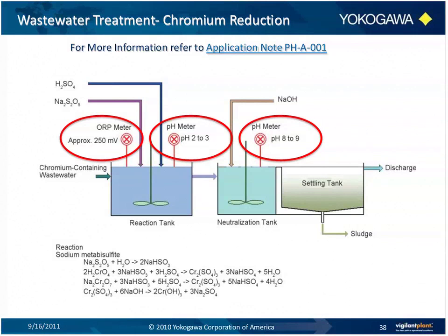Precipitated out as chromium hydroxide. As the oxidation reduction potential and the speed of the reduction reaction are closely tied to the pH value, ORP and pH meters are commonly used to ensure proper control of this reduction process at the different injection sites of the reducing agents.